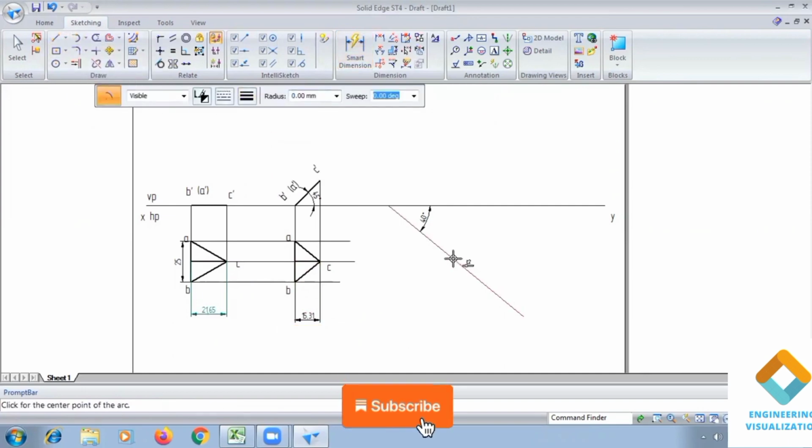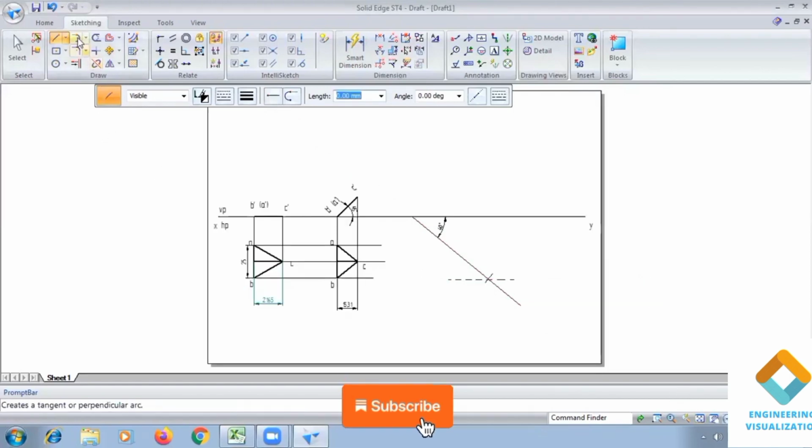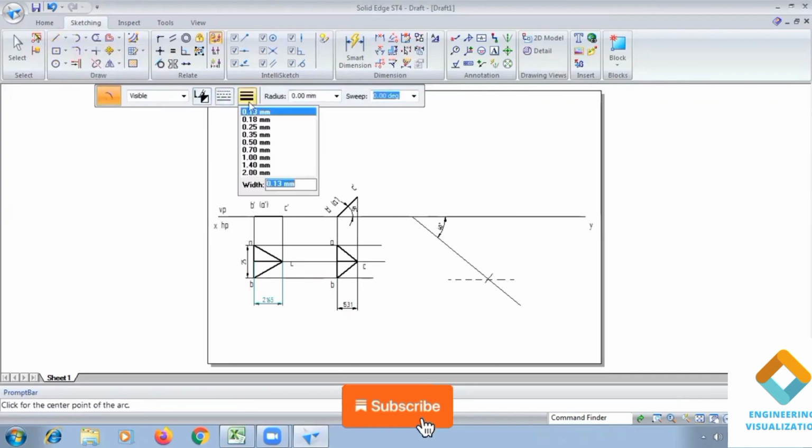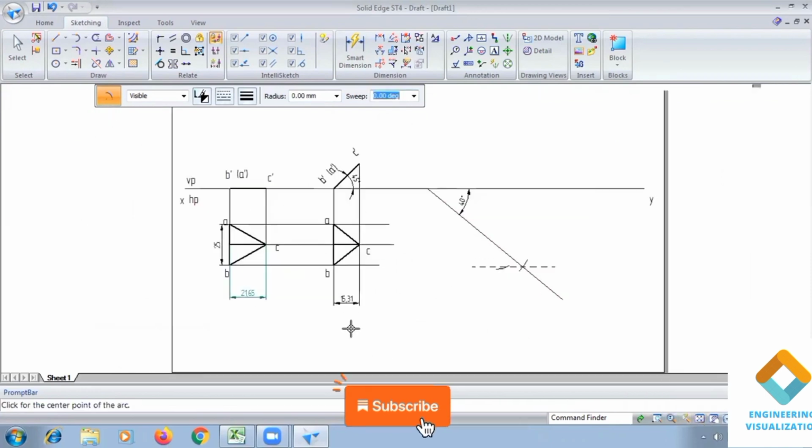So go to arc by center and cut the first arc of 21.65. Cut the arc. Now draw the locus line. Let's draw the locus line here. Again go to arc by center here. So take second arc length 15.31. Okay, from this reference point, type radius 15.31, enter and cut the arc. Okay, now join.